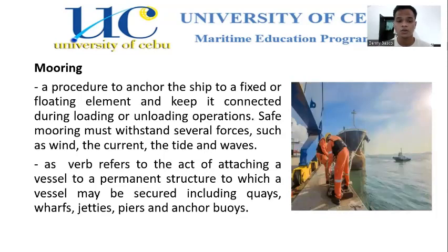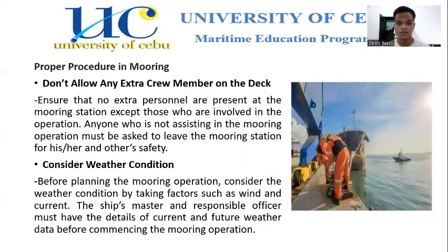Mooring is a procedure to anchor the ship to a fixed or floating element and keep it connected during loading or unloading operations. Safe mooring must withstand several forces such as wind, the current, the tide, and waves. As a verb, it refers to the act of attaching a vessel to a permanent structure to which a vessel may be secured, including quays, wharfs, jetties, piers, and anchor buoys. Here are the proper procedures in mooring.